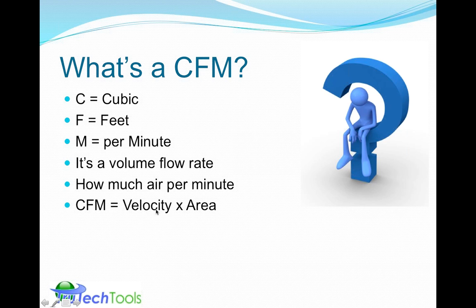So getting both of these right helps improve how correct your airflow measurement is. Someone asked the question, do I subscribe to the 2 square feet of return air per ton? I do not subscribe to most rules of thumb, because with just a couple more calculations and understanding the science a little bit better, you can actually nail the answer. Usually rules of thumb are good over a short range.